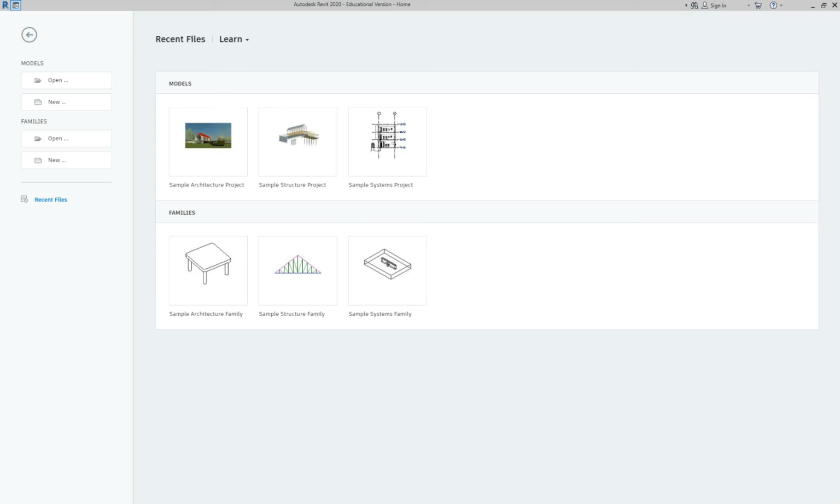Okay, good. So some of the things just to consider before you get started. So the construction. And you know what one of those answers can be? It can be a 2x4, it can be a 2x6, it could be brick, it could be CMU. And the best part about Revit, you could also not know. There's something called a generic wall type that you can put in and use that as well, okay? So just consider the construction of the wall.